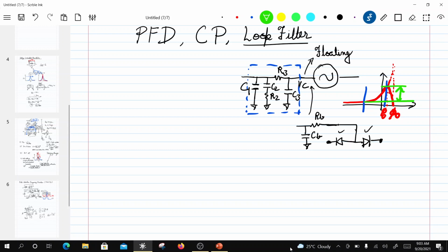Now what happens is, at high frequencies I have no issue. Over here there is going to be high frequency because the capacitance is low, and here I don't have an issue. The issue comes at lower frequencies. At lower frequencies, these diodes start getting forward biased, and this causes the current to be pulled from here, and this causes these capacitors to lose the charge.